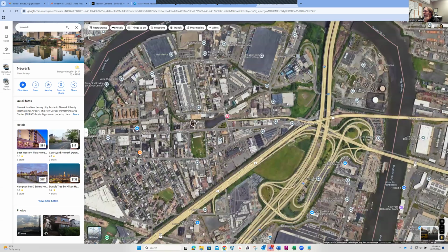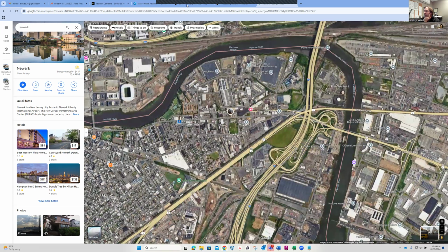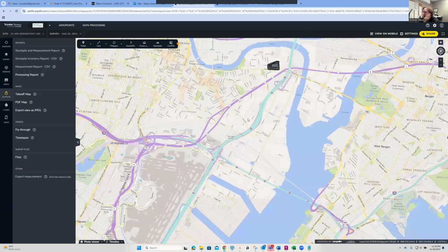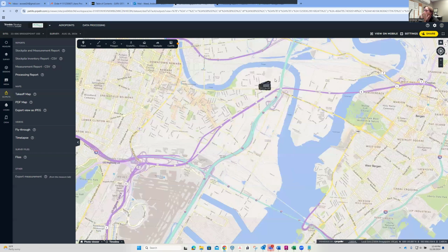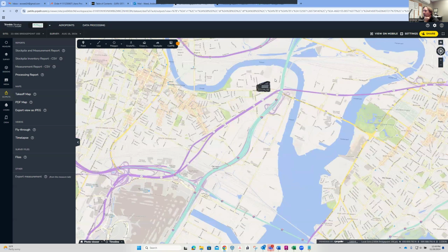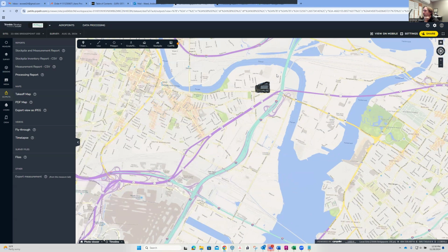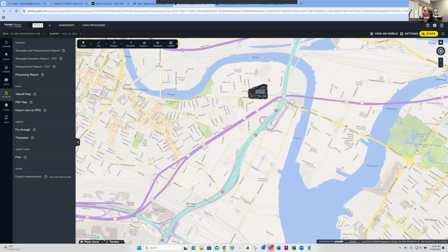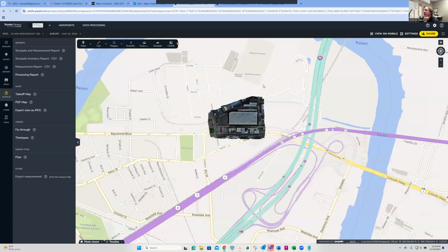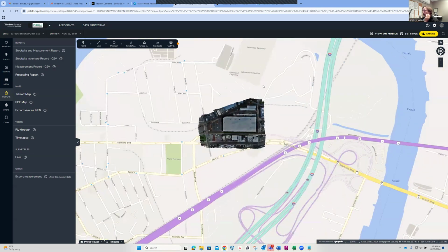Yep, so this is our project site, and we actually ended up building a new warehouse facility, my particular construction company. We utilize low-level aerial drone photogrammetry to help us with earthwork quantities and as-built mapping so that we can verify that the site was built in substantial compliance. We obtain the aerial photogrammetry with a low-level drone flight, but then we offload it to an online service that stitches all the photos together based on the ground control that we provide and creates an orthophoto.